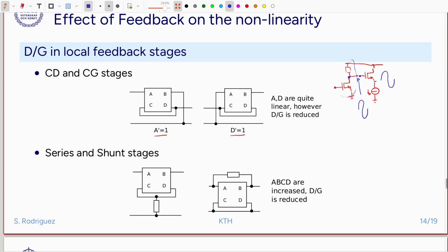Okay, and think about this. The output transistor will see very large signal swings both at the input and on the output. And in addition, it's going to be stressing the output. The output voltage swing of the first stage is also going to be affected, introducing nonlinearity. So this is one of the issues of using a buffer, and it can be a voltage buffer, or it can also be a current buffer at the output.